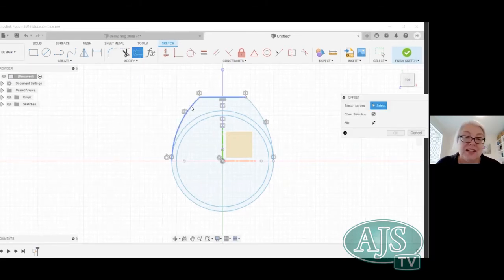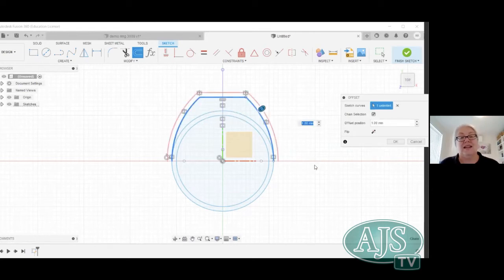So we want it to do that and that. And we actually want it to be on the inside. So we flip it. There we go. And let's say we want it to also be that 1 millimeter, that -1 millimeter again. Now the minus just means it's internal or going inwards. The plus means it's going outwards. So if I were to flip that, you'll notice it becomes a positive value, and that would try and set down a curve outside.